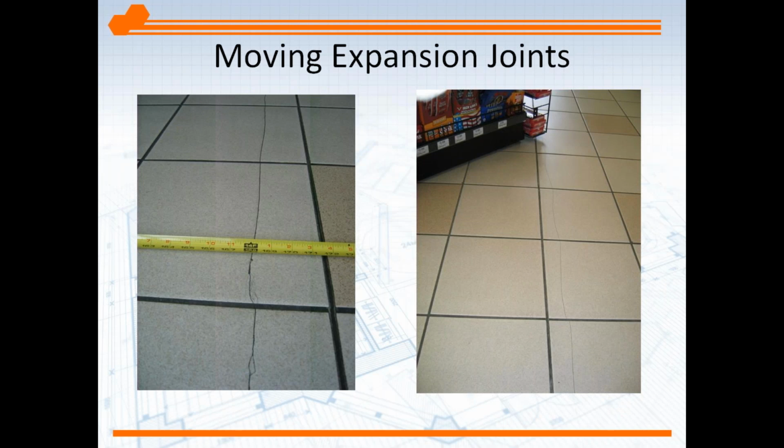The picture on the right is the same picture, just from higher above. It looks like a different color, it's just a shading. But like I say, unfortunately, that joint really needs to be honored directly through the tile when there's a joint in the concrete like that.